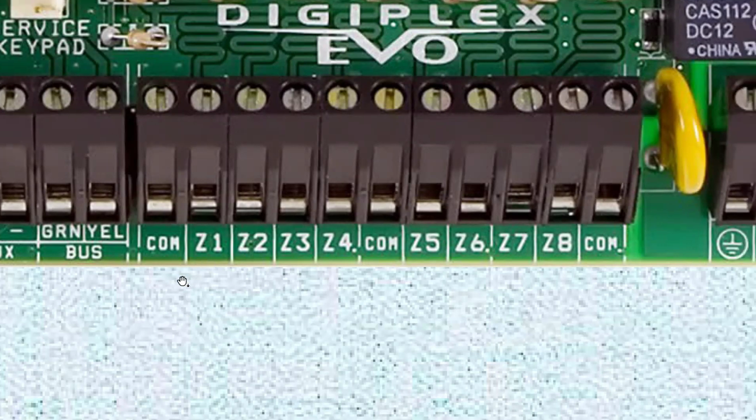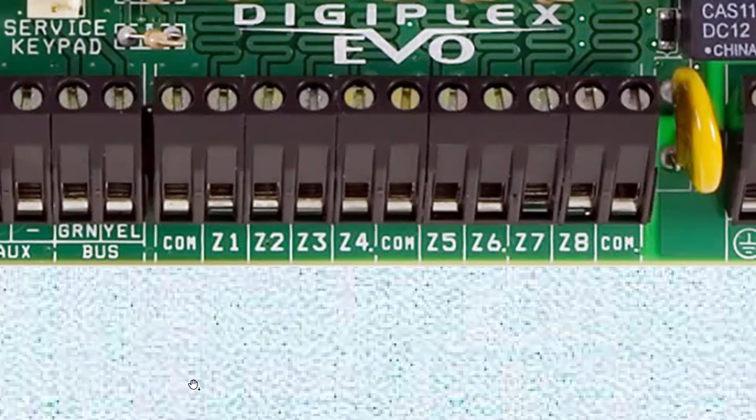So let's say usually, zone 1 is being installed on the main entrance, right by the keypad. Zone 2 could be, for example, all the windows in the living room. And you'll be connecting them in series. So from zone 2 to one window, and then in series to another window, in series to another window, let's say 3 windows, and then you're going to come back into common. So you're going to have a loop of 3 windows connected to zone 2, and you can label that zone living room windows.